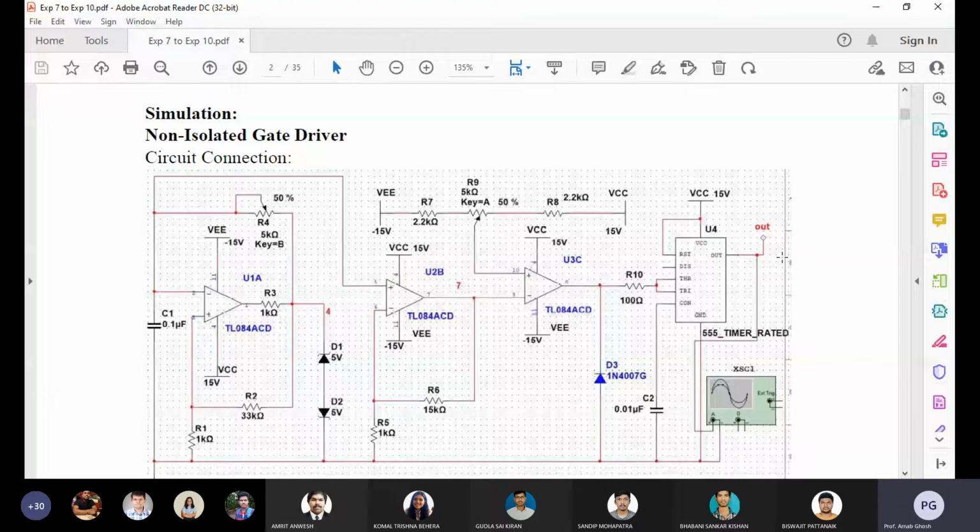So how do you minimize that error? You have to make the on time of the switch longer to compensate for that error. So the logic is that the on time or pulse duration will be more. That's why you need to increase the pulse value.